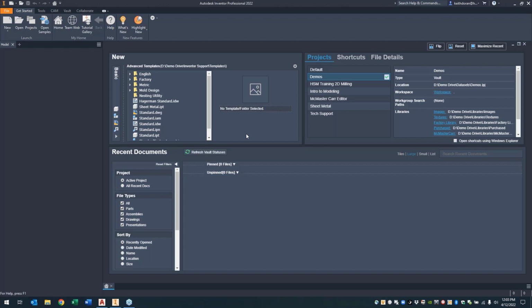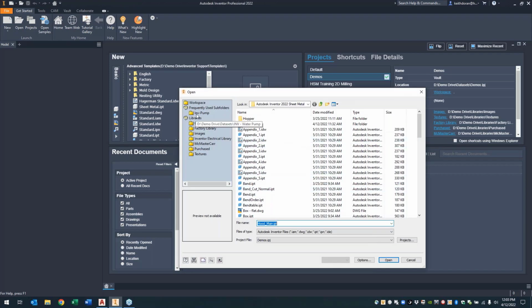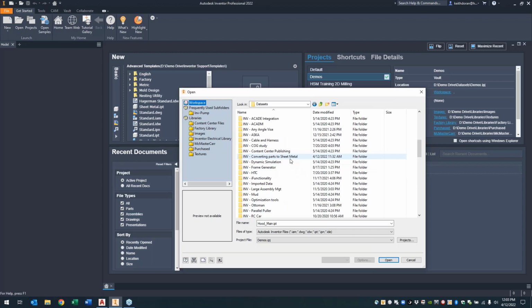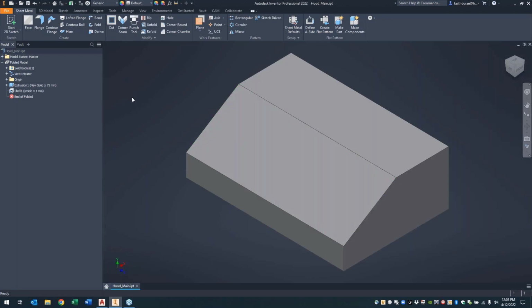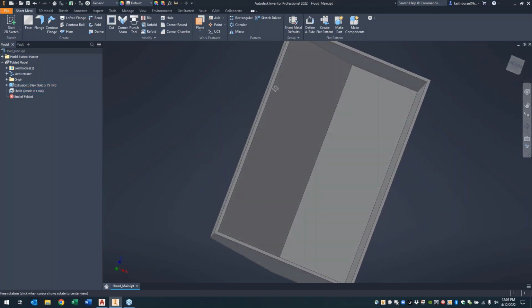So when we go through this process, we're thinking about linear or roll form shapes in order to get the flattened profile shapes out of them. And so with that ideology in mind, just some different things that we can look at when we work with parts. So the first file that I want to open up here is just a basic Inventor part file. And in this case, this model has not been created using any kind of sheet metal functionality at all, right? It's just a standard extrusion profile and a shell to hollow out the bottom side of this component.